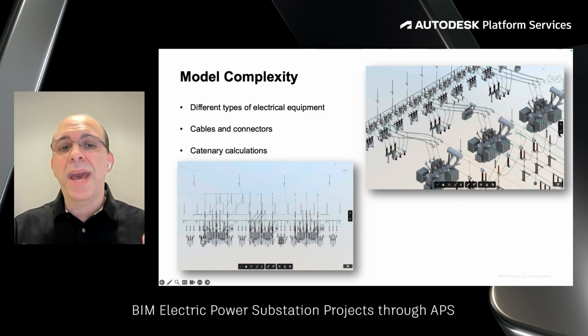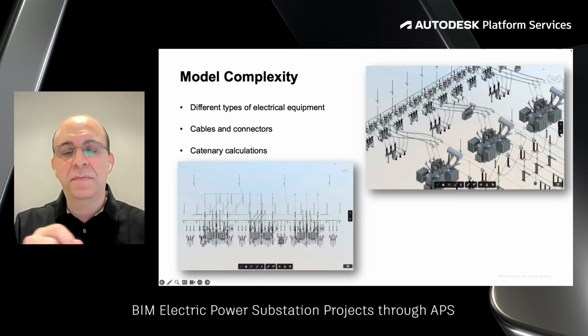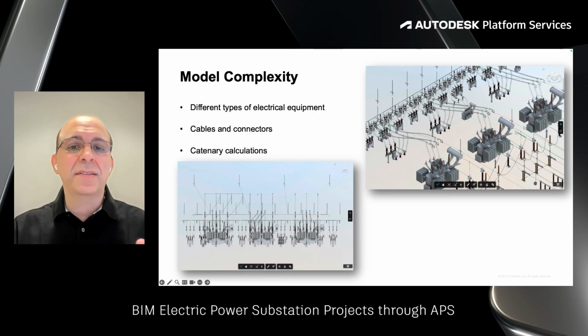So here we are also embedding engineering tools inside this plugin because it looks simple, but all this cabling needs to go through an intense calculation process to determine the appropriate curvature of those cables because they need to have clearance from other equipment. Remember, we are talking about high voltage, so it creates a huge electromagnetic field around those cables and equipment. So it's a very delicate process to design these substations.